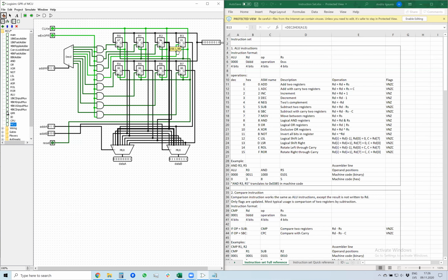But if we wanted to use signed numbers, then 158 cannot be written in 8 bits. We can write only from minus 128 to plus 127. This number is greater than 127, so it wouldn't be a correct number in 2's complement format in 8 bits. This is why you were seeing minus 98.